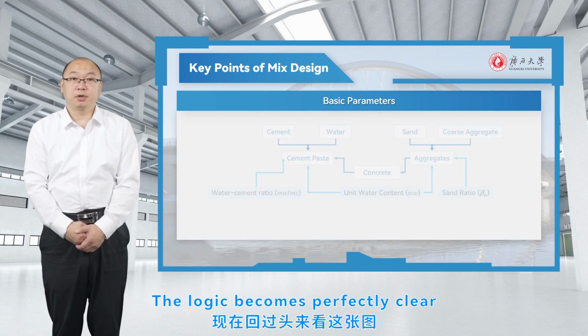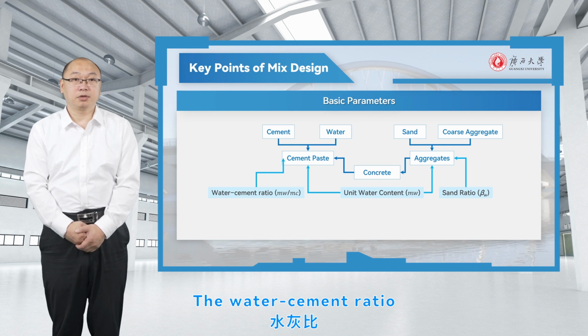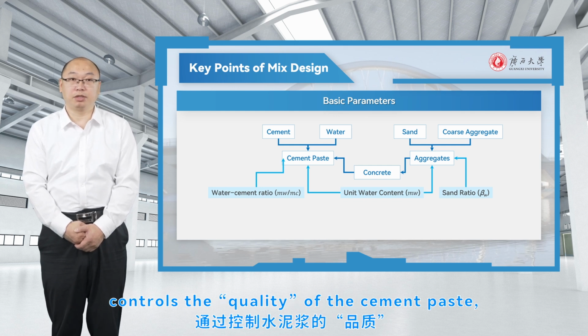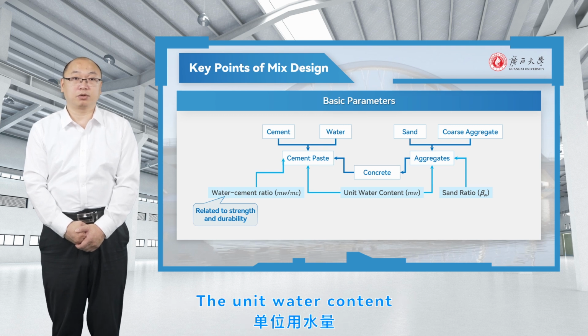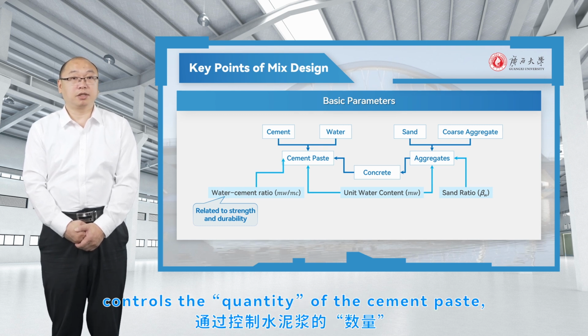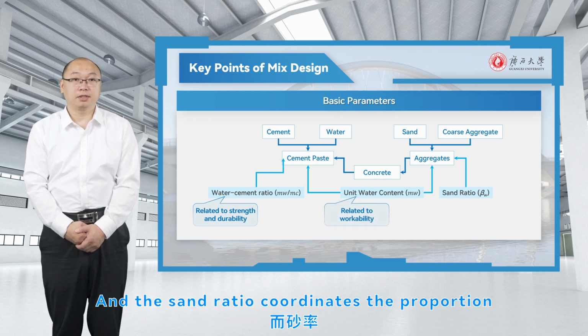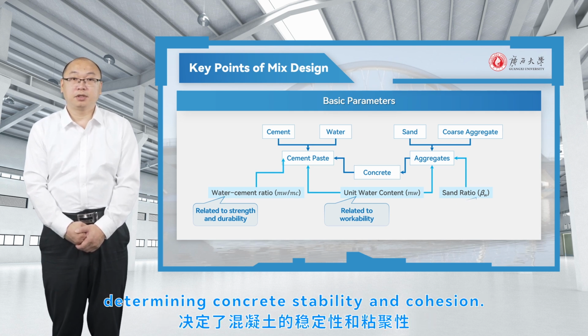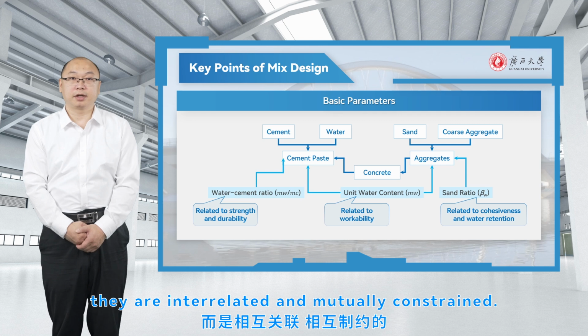The logic becomes perfectly clear when we look back at this figure now. The water-cement ratio controls the quality of the cement paste, determining the depth of strength and the breadth of durability. The unit water content controls the quantity of the cement paste, determining workability during construction. And the sand ratio coordinates the proportion between the skeleton and the filler, determining concrete stability and cohesion. These three parameters are not isolated, they are interrelated and mutually constrained.